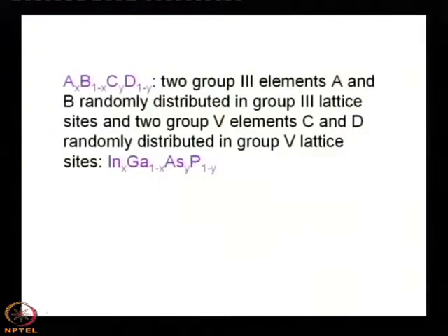The electron or hole concentration will be different during doping. So, I am not talking about doping, it is not related to doping, it is related to band gap engineering where new materials are formed to tune the band gap for a particular application. Say for your fiber optic communication, you need 1300 nanometer or 1550 nanometer sources. So, you have to make a new material with such composition, so that its band gap will be matched with that.